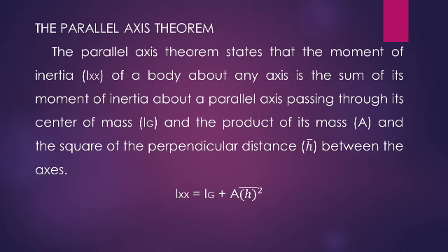Ig is nothing but the moment of inertia formula for each shape. If it is a rectangle, then the formula for Ig is bh cube divided by 12. Same like that, the area for the corresponding section. If the section is a rectangle, then the area of the rectangle is L into B, length into width.